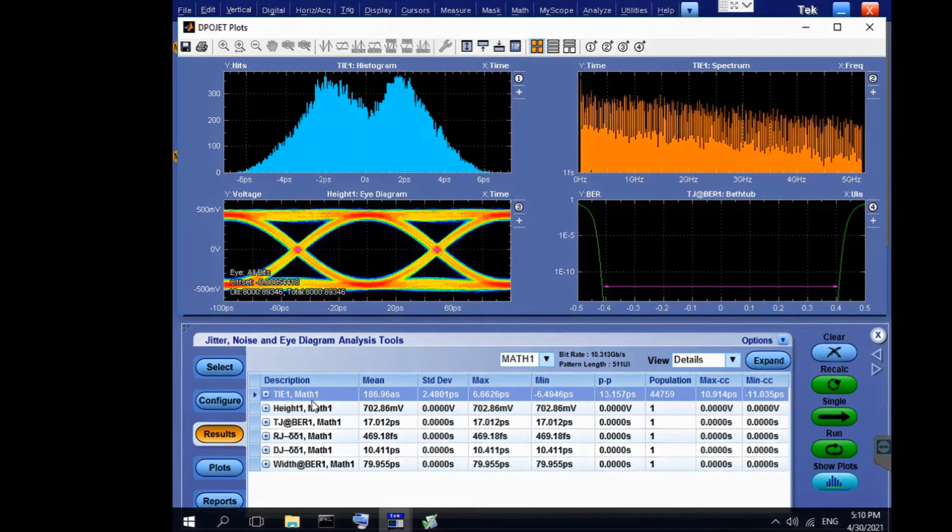And then you will have advanced analysis behind that, which can be spectrum based or tail fit algorithm, depending on the case, that will be used to extract the random jitter component and the deterministic jitter, and then that will be used to extrapolate using the random jitter RMS.